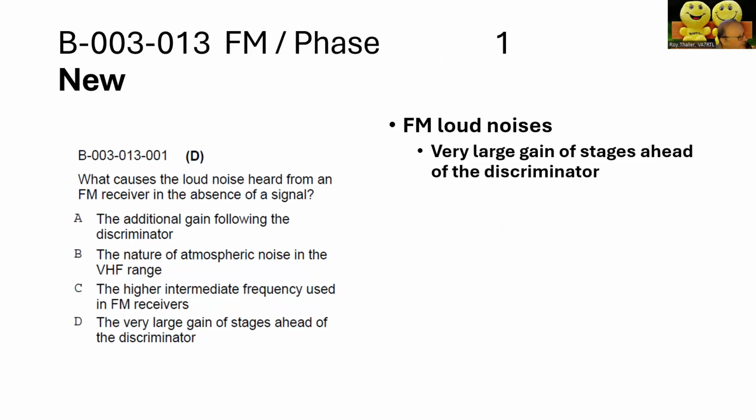A new question. Now we're getting into FM modulation and phase modulation, although phase modulation is generally not used in amateur radio. What causes the loud noise heard from an FM receiver in the absence of a signal? So that is because of a very large gain of stages ahead of the discriminator.